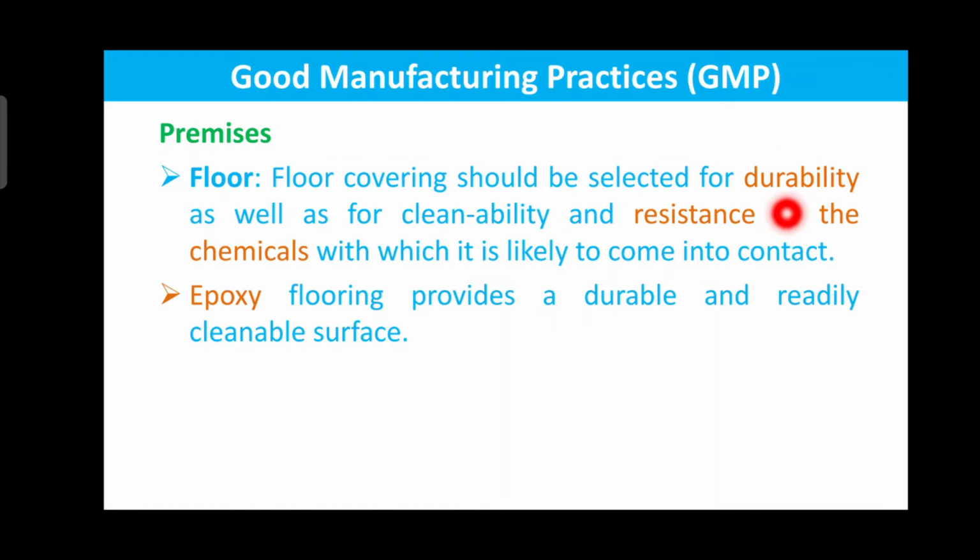Again, this is all general common sense. The floor has to be durable, as well as cleanable and resistant to the chemicals, since it is a manufacturing premises, so it has to be resistant to the chemicals with which it is likely to come in contact. Then epoxy flooring provides a durable and readily cleanable surface.